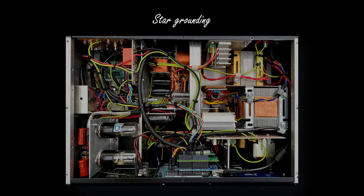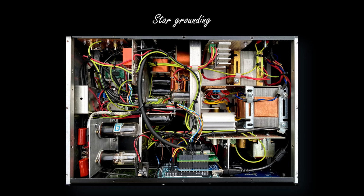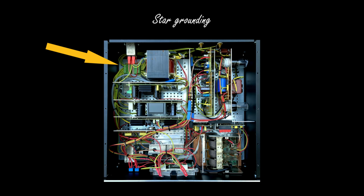Of course, there are several degrees of precision. I would say the extreme solution would be to have really each and every grounding connection within the amplifier with its own ground wire to the central grounding point. This will work for sure, but might be a little bit tricky to implement.